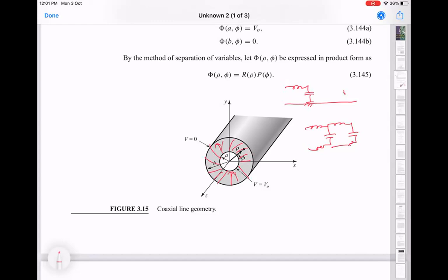So within the transmission line itself of that connector, you're going to have different parts having different properties in terms of the construction, but everything has to be 50 ohms, otherwise you'll get reflections. Those connectors also tend to be a lot more fragile, because the center thing is now being held together by some very thin dielectrics at two ends, and if you push it too much, you can actually break the connector. So we will look at connectors at a later stage.